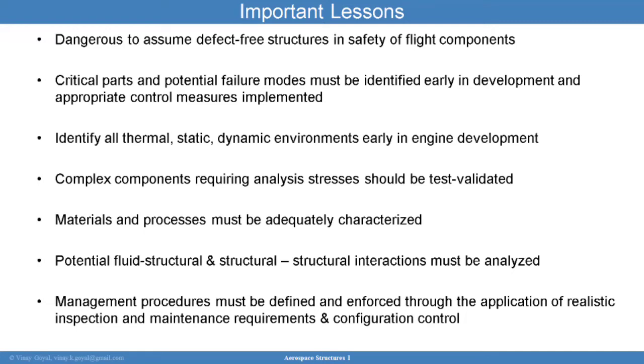Anytime you're working on a component that has a lot of moving parts, or the joints are quite complex, and hand calculations are okay, but you don't have certainty in these hand calculations, it's important to perform testing. Subscale testing, not the full-scale testing of the whole aircraft, but testing portions of the aircraft or launch vehicle or spacecraft, so you don't spend too much money failing a large-scale composite or large-scale airplane.